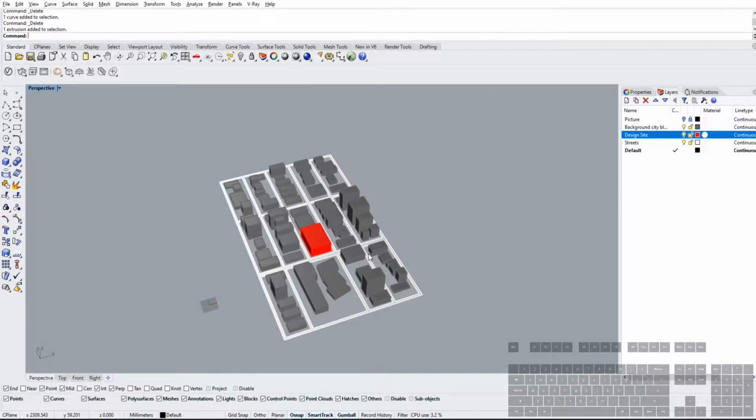And for the next few steps, we really want to make copies of each one because we'll need a drawing for each step. So we'll need a copy of the actual model for each step as well. Now, how I like to do this, and this is totally up to you guys, is I just like to drag it to the side, maybe by 3000, just so I have a copy of this and I know that if I wanted to move it back into place, I can do that.